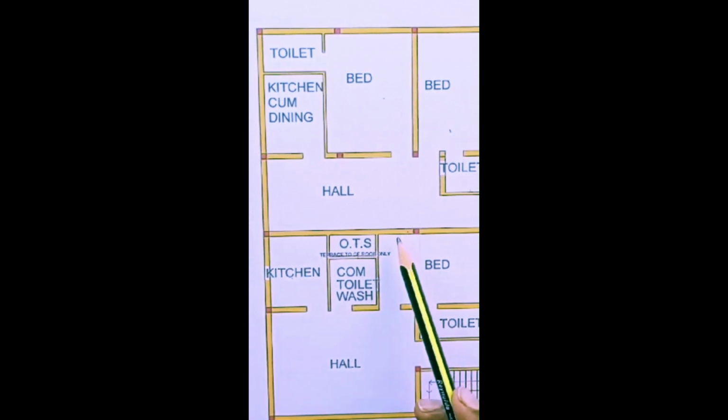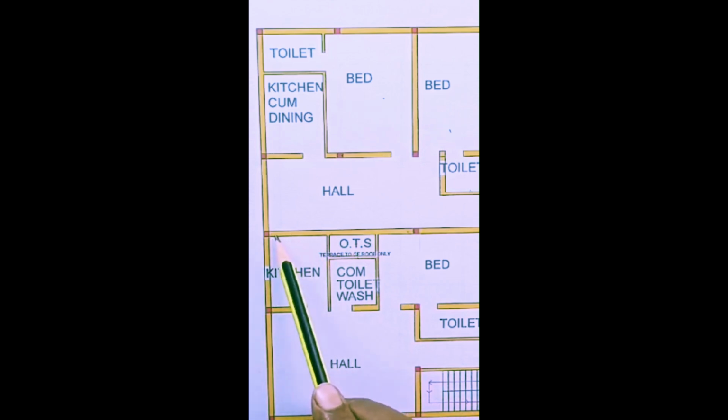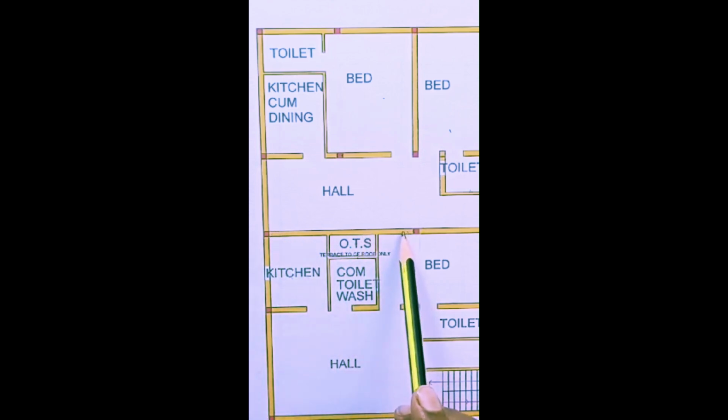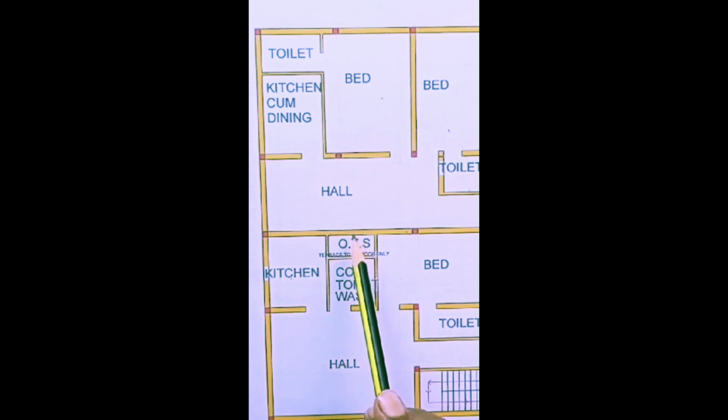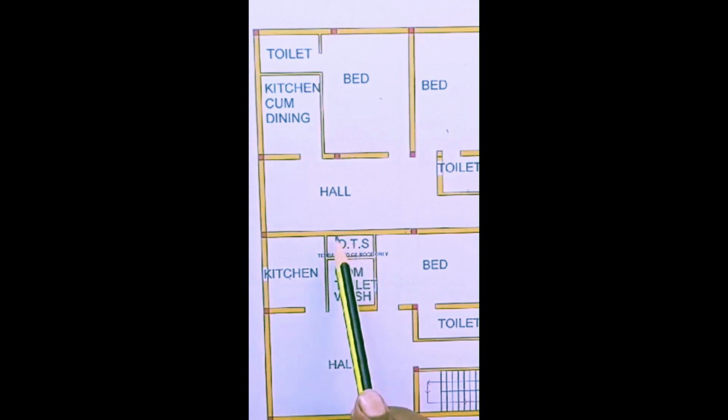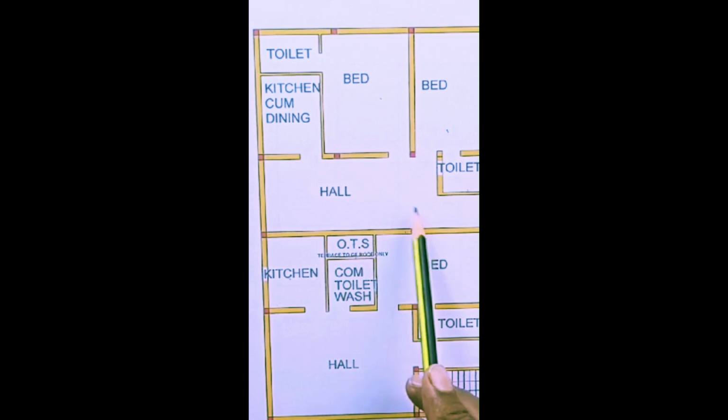We are going to provide this beam, but the web of the beam will be given on the upper side of the slab, because the wall is going to come on the first floor. So the wall can be constructed above that web of the beam. That web is not a problem for utilizing the upper floor area.